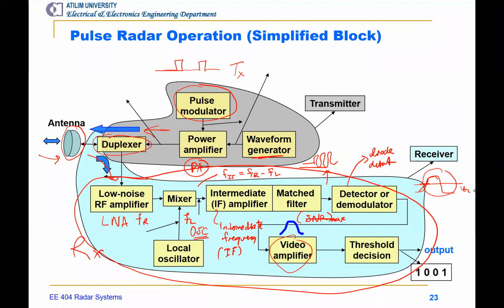There are two main things inside, actually. For example, an antenna: you have to move your antenna. There should be a servo mechanism to control the antenna and sweep in azimuth and elevation together, or just one dimension. That's one thing. There should be power circuitry, a power supply to power all of this. There should be some control circuits to switch between two components or to synchronize different components.